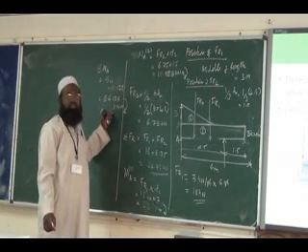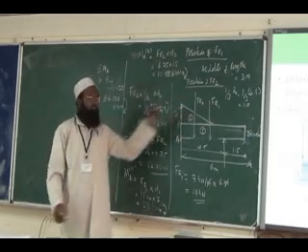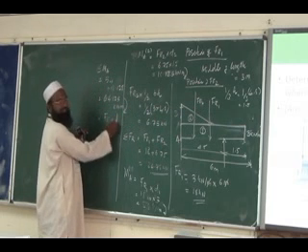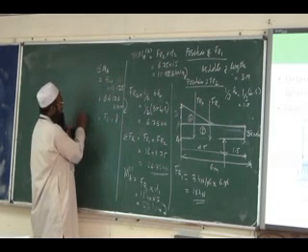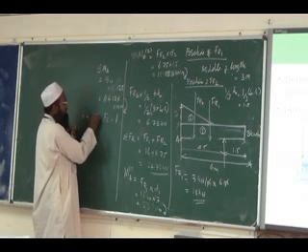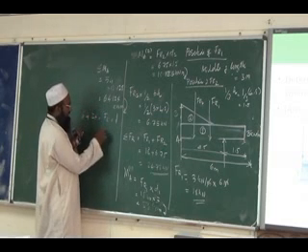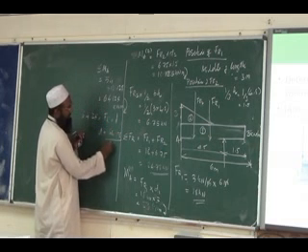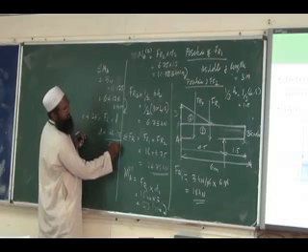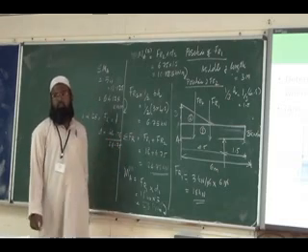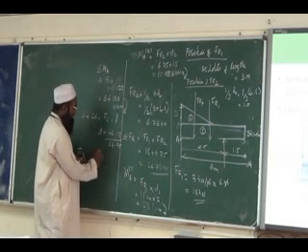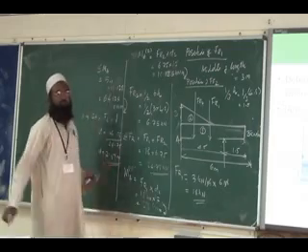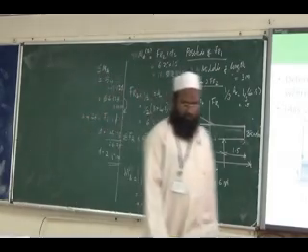The resultant moment is produced by the resultant force. So this resultant moment is equal to FR times T. Or we can say 64.125 is FR times T, and T is 64.125 divided by 24.75. So we will get the T value, 2.5. So we got the position for FR.